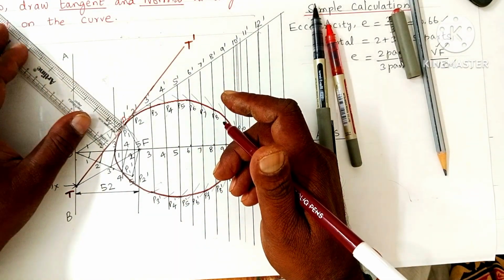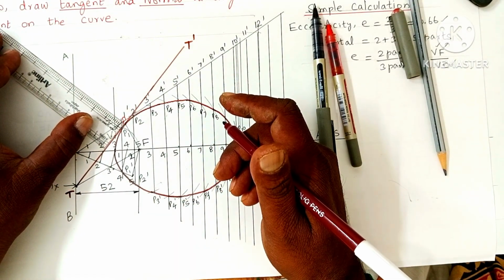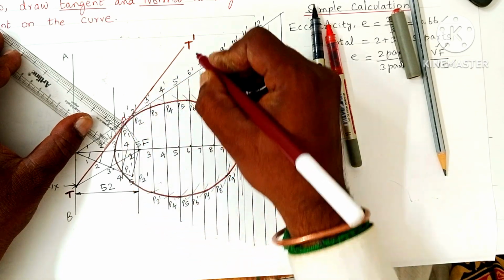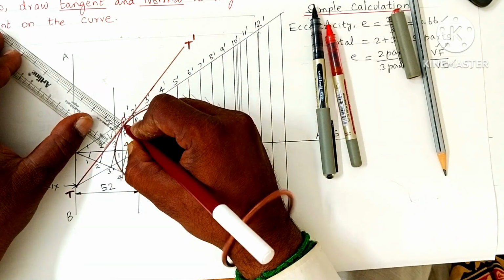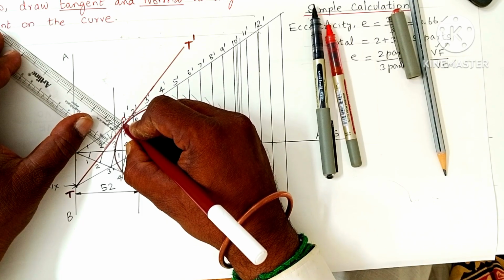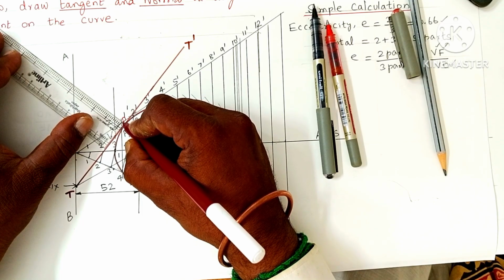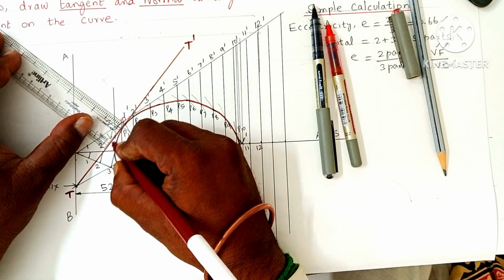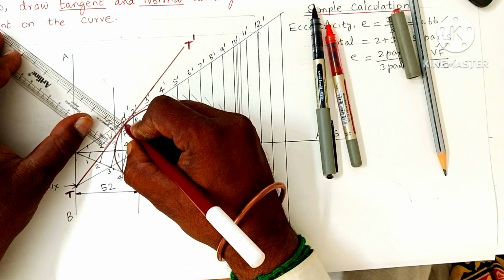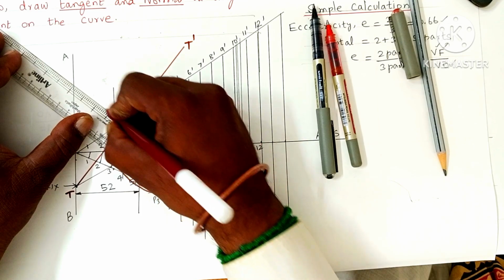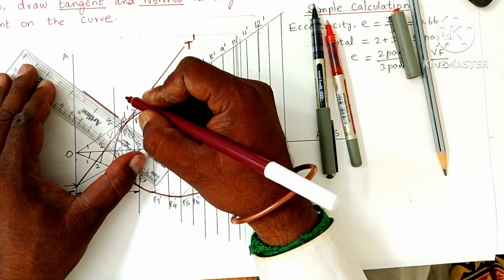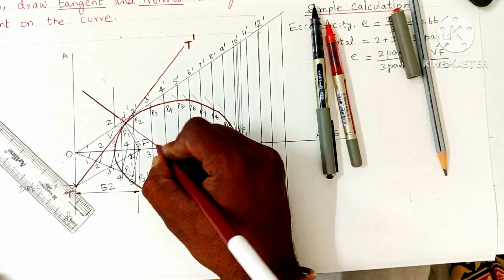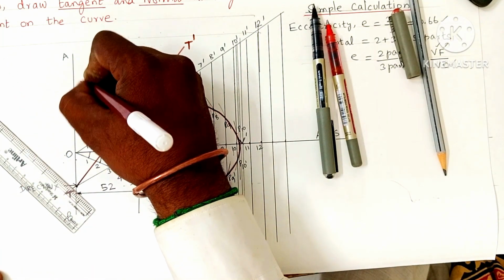Here I use the ordinary scale itself. So draw a line perpendicular to T dash at point P. The corner of the scale must coincide with the located point P. The smaller edge of the scale should coincide with this T dash line at point P. Using another edge of your scale, draw a line like this and extend this line further, that is, below the point P. This will be marked as N dash, called the normal.